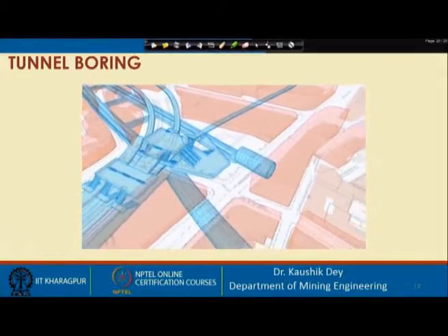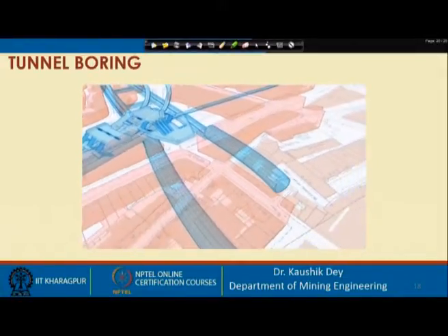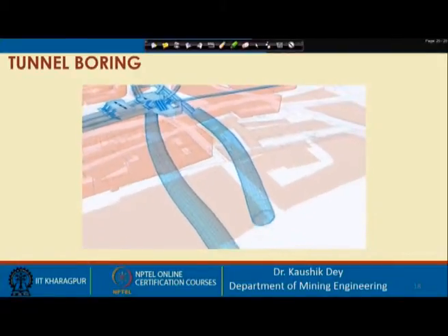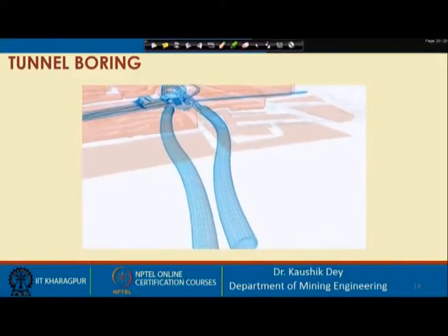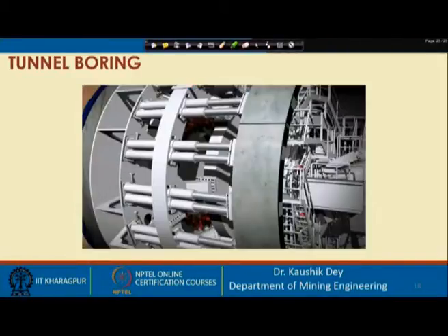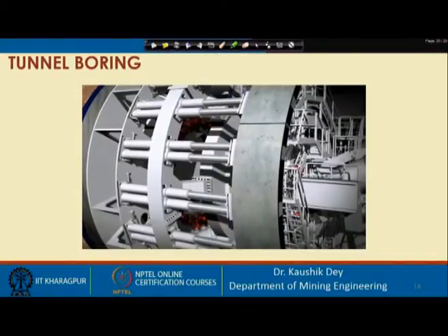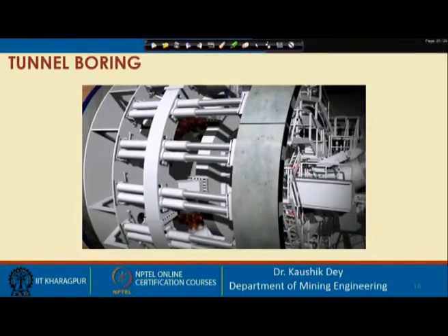So, the tunnel ring is built in a slightly conical form. This means that horizontal curves can be built along the tunnel route by changing the advance direction. In conventional methods, hydraulic cylinders are extended again to secure the segment into position.